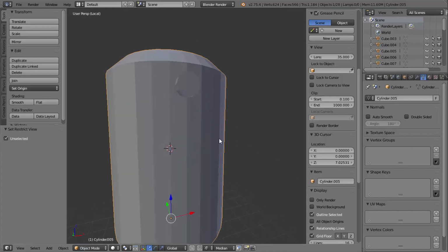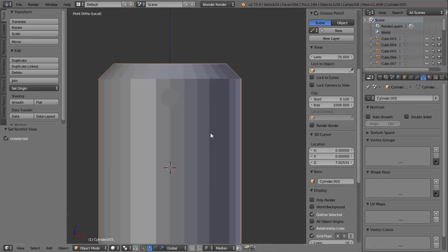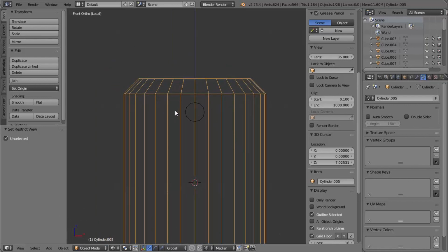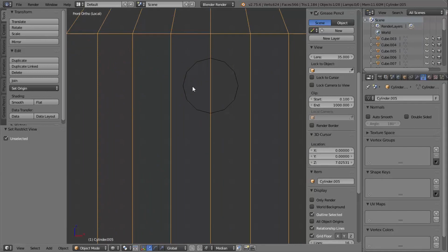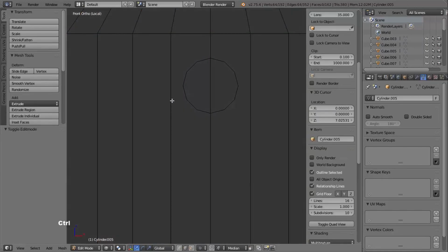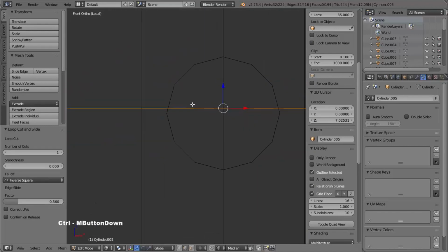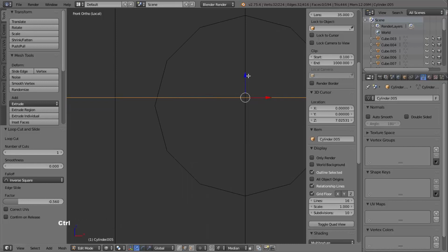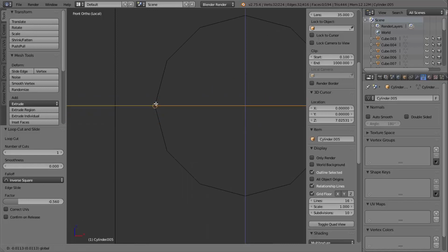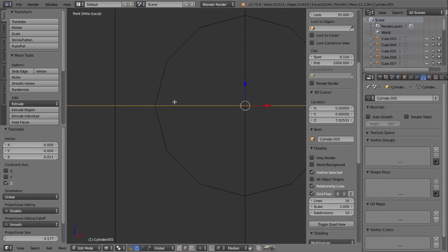And now I want to select the large object and go into my front view and wireframe, and I want to cut a new edge along near the top here to snap to the central vertices in this new cylinder. So I'm going to go into edit mode and then press Ctrl R and then just click and place an edge near where I want it to be. And then I can hold Control and click on the blue arrow and then snap them to the center there.